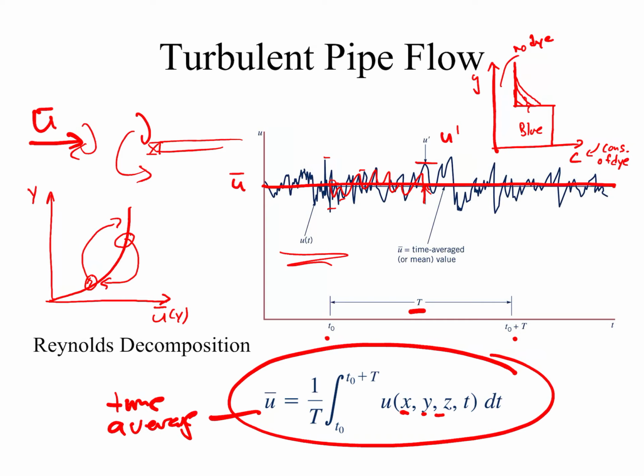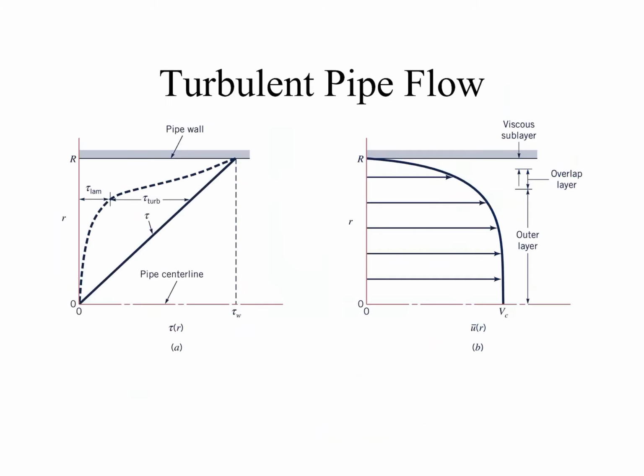But for a turbulent flow, the eddies act to really mix up this interface and very quickly degrade this gradient so that it mixes much more rapidly. So we want to think of turbulence as mixing and degrading gradients in the flow field, whether it's momentum or other scalars. And so that is going to make a big difference in what our flow looks like.